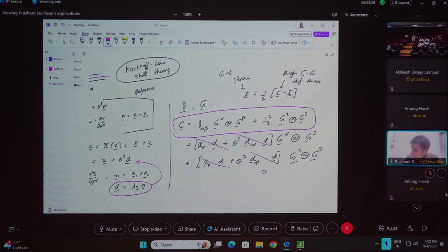So the first term here basically looks at what kind of deformations happen in plane. You're stretching it, whatever happens to the surface, the deformation of the surface itself. And the second term is talking about the thickness direction, whether it is thinning or becoming thicker. So these are the only things that come in. And then using this, you can calculate the strain tensor, which is here.